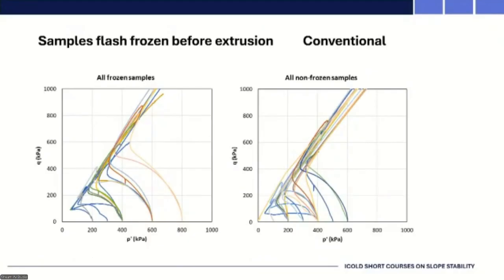I've spoken to the drilling contractor, really important that you speak to the drilling contractor, and he said to me they would push the sample tube into the ground, and then they would wait for dissipation to take place, sometimes an hour, sometimes 2 hours, and then they would pull the sample tube back up. Then they would put caps on and everything and store the sample. But quite often the sample would drop out and then they would try another location. The samples that dropped out are the samples that we want.